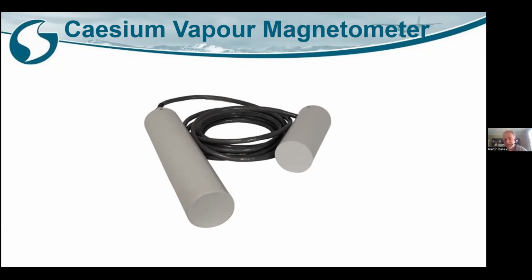It is possible to measure the vector of magnetism in the air, but it is difficult and more challenging. So for the majority of magnetic surveys, we're just measuring how strong the magnetic field is, what its overall intensity is. And this magnetometer emits a pulse of frequency, which is directly related to the magnetic intensity.